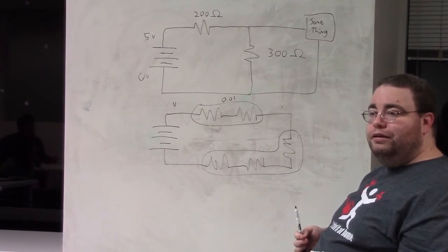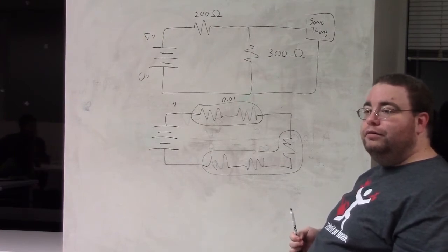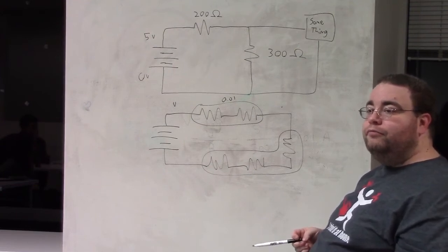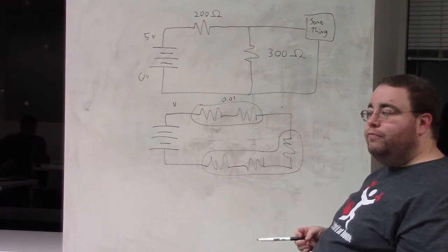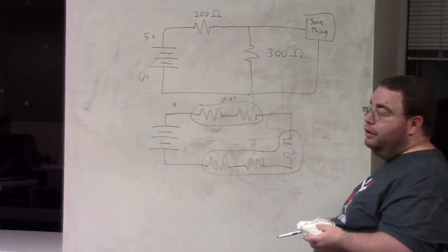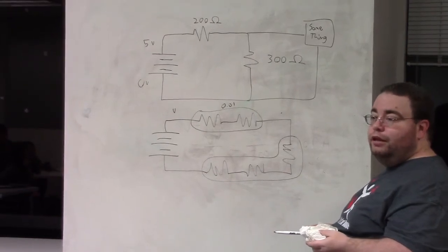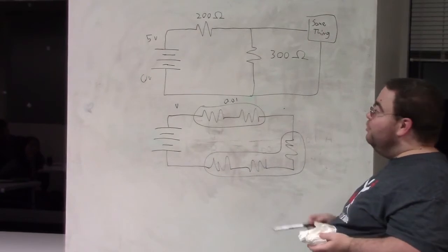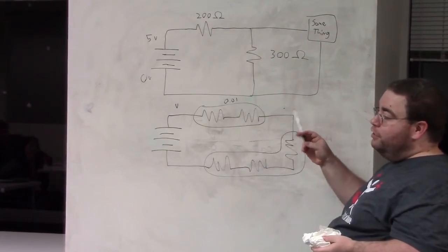There is a feedback that compensates your loss at the end versus what you need, so it pumps more current to keep that voltage. It's just a more efficient way of getting the drop, because there's more circuitry in it to regulate. On the other hand, it's a bigger, more expensive part. So whenever you can use a voltage divider for something that's not using a lot of current, then it's